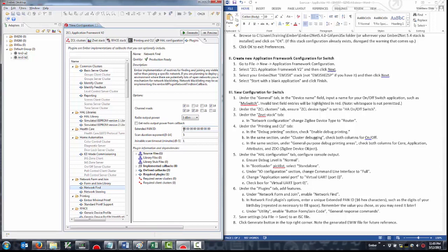So that if you have a multitude of lights and switches running these examples, you won't have devices colliding with each other and joining the wrong network simply because those networks are open. If you're running this on your desk by yourself without any other ZigBee networks in your office, without fear of other networks that may be open, then you'll probably be okay without changing this.